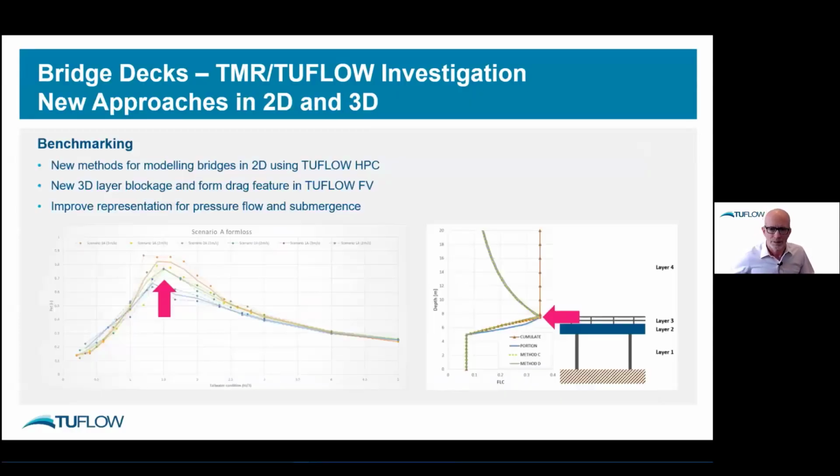What we've been doing in TUFLOW is trying to replicate that shape, which is coming out fairly consistently amongst the CFD modelling. You have to rotate your head sideways, but this replicates that similar shape. You can adjust how this moves and set this inflection point as well.